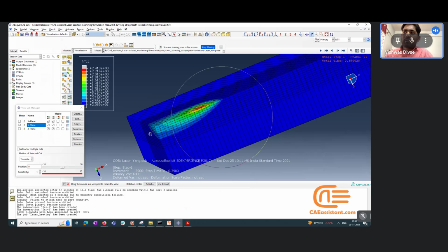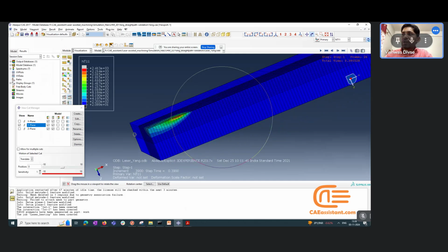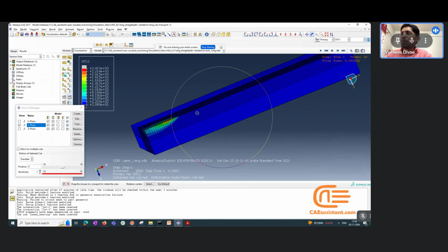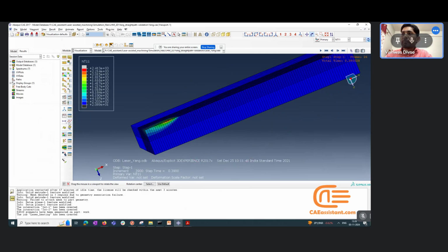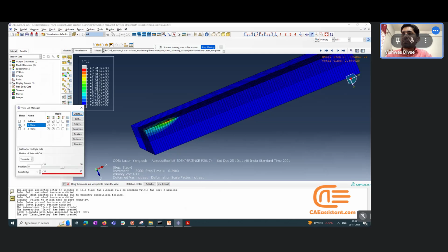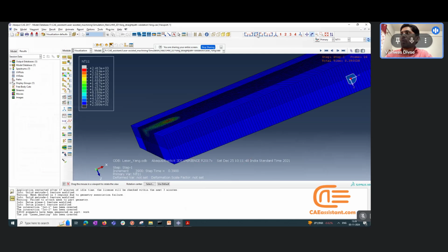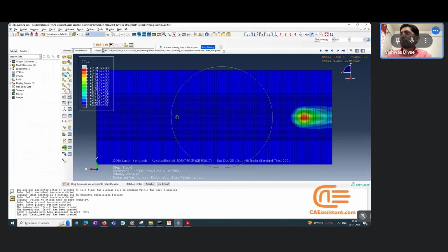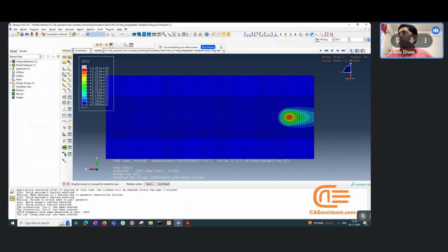In the latter part, the same softened zone we will remove using the cutting tool. So that will make our laser assisted machining. And the results we can even verify. I will show you quickly. Okay, we'll go in default orientation. See, let's say after 5 seconds, what are the results? I can choose the frame number here. Here you can see the time. So if I go slowly, the 0.49.